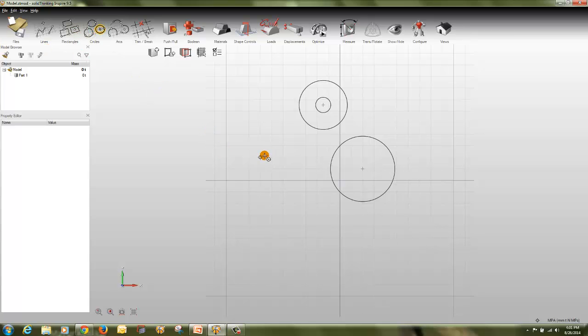Then circle with center. This is the center. Whatever you change, it will go around the center. You can have 75 as the dia, whatever dia you want, and also you can change the dimension. You can also change the center, reduce the dimension.